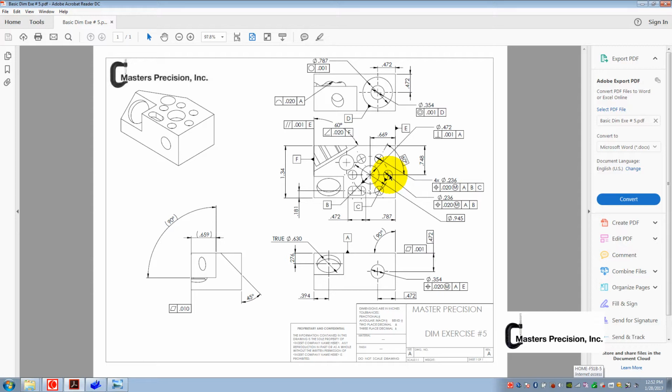We're going to be measuring a plane, setting reference, defining datum A. Then I'm going to measure B, set reference, and define datum B. Then I'm going to measure C, and I'm going to draw a line through B and C. And I'm going to reference off of that line and define that as datum C.